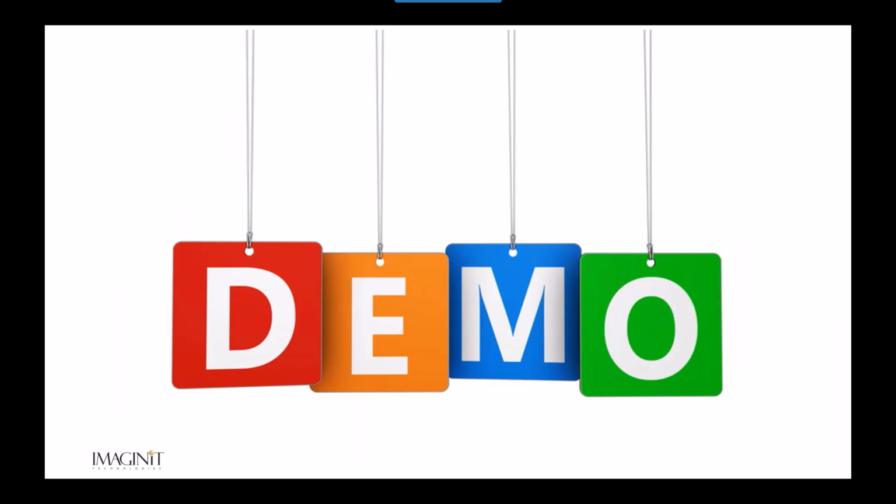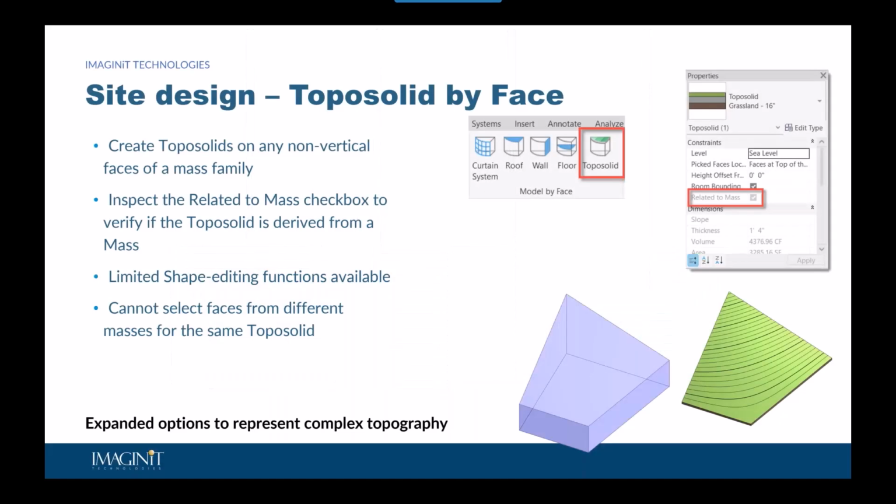Moving on to the next demo, we have Topo solids by face. Another new site design feature is the ability to create Topo solids on any non-vertical faces of a mass using the Topo solid by face tool. You can inspect the related to mass parameter to verify if the Topo solid is created from a mass or not.